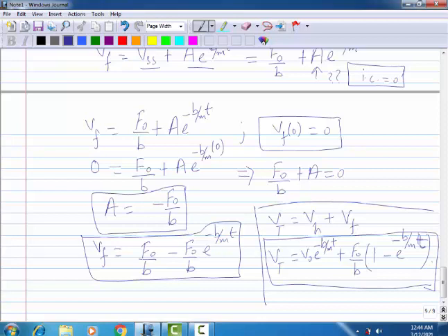Now my question is again, if I ask you to plot the force response, how does the force response look? Let me plot here. Because we are reaching F naught here, and because force response normally starts from 0, it will start from 0 and try to reach this equation. And this reach becomes 1 minus exponential of minus B by M.